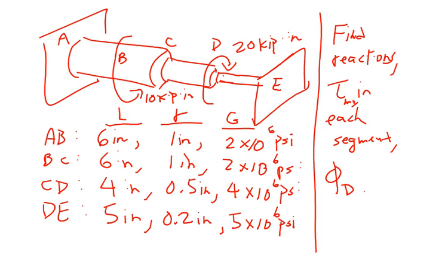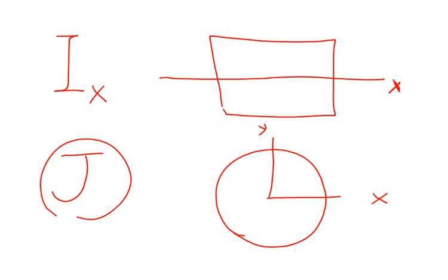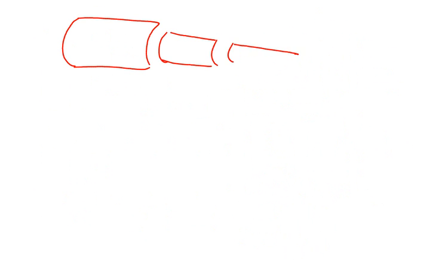And then the second part is to look at the effect of the supports, the reactions exerted at those supports. So then you just put back in the torque that was applied by that support that you have removed in the first part. Okay, so let's break this up, right? The first part of the problem then is to simply look at the case where we have the applied torques.